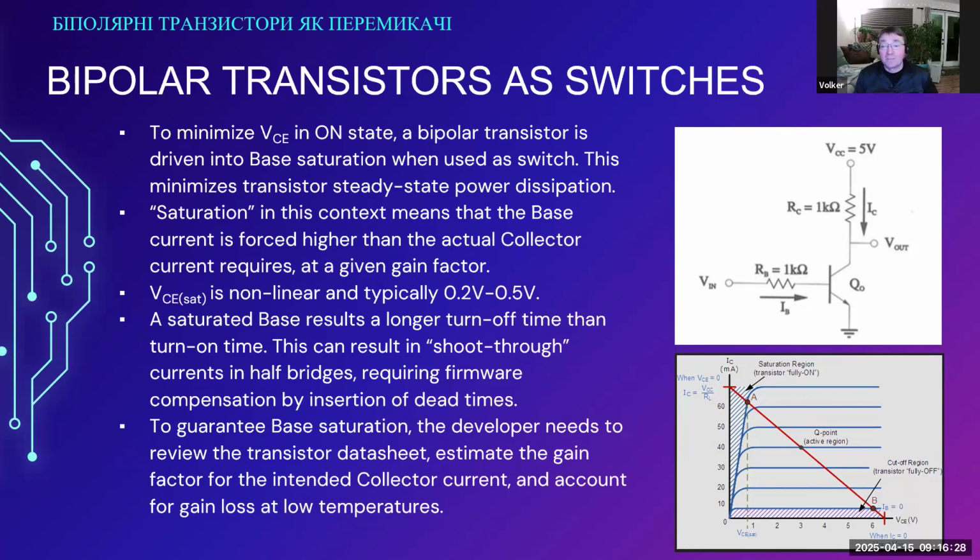But for example, if we're using two transistors, and we are trying to counter switch them, turn one on while we're turning the other one off in a bridge configuration, this might be a problem because suddenly we have a microsecond where we are getting very steep current spikes. So this might require fixing in firmware.